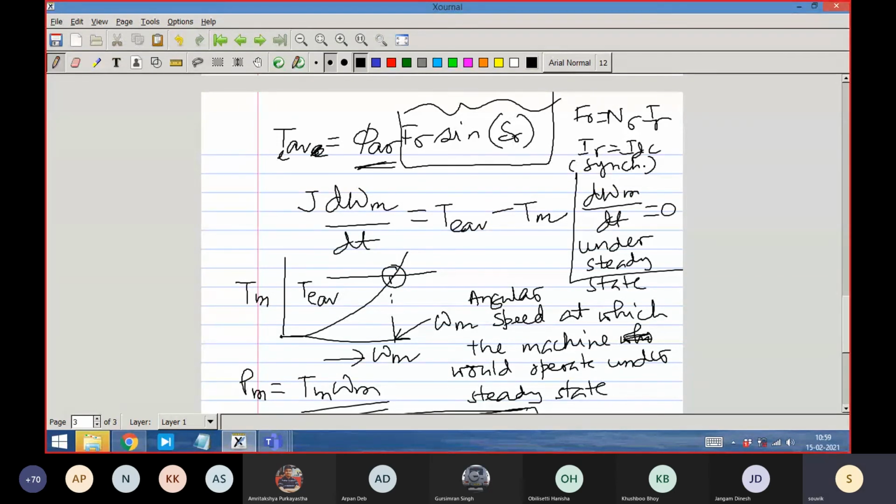Electrically, you will see that the voltage and the current will be changing, adjusting itself, and the power factor will be adjusting itself to formulate this VI cos phi. From the electrical power point of view, VI cos phi has to be equal to FR sine delta R. I will come back to that. This is how you will realize it, because internally we do not see the flux, we cannot see it. It will happen, this angle will happen.